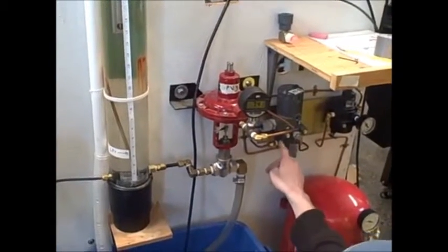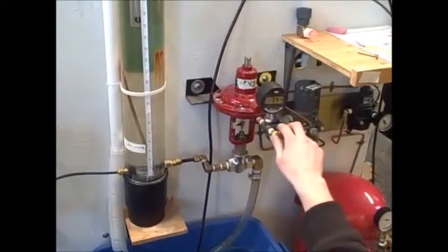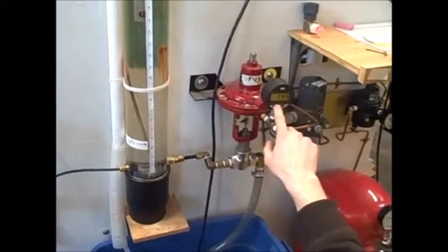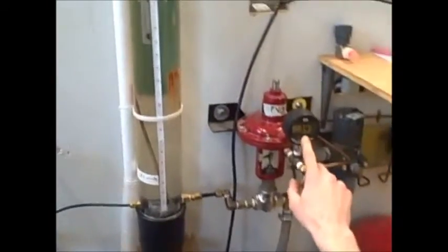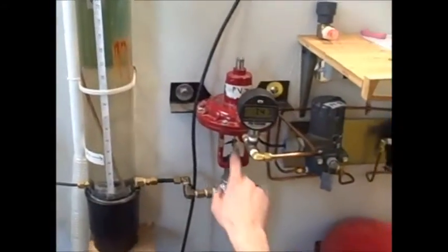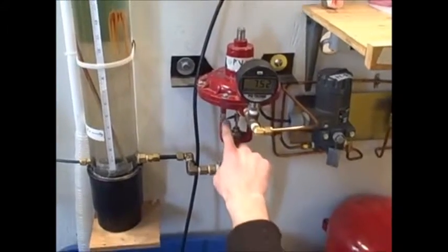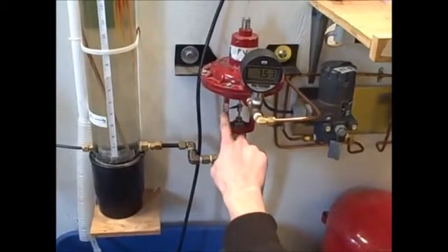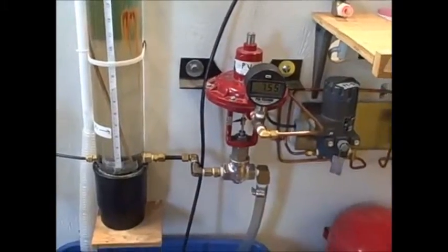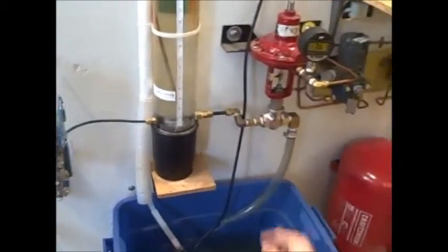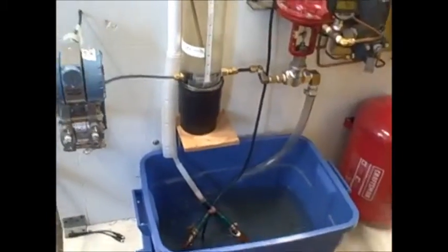And then that pressure output gets sent to this control valve, and you can see the pressure right now is about 7.5 psi. The pressure pushes down on this needle, which controls the valve, and you can see the indicator level is a little less than 50%, which permits a certain amount of water to flow through there to maintain a level.